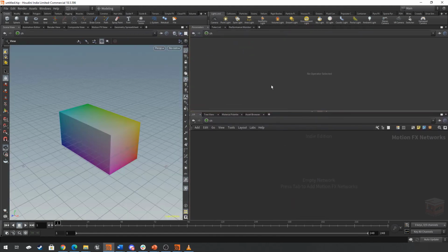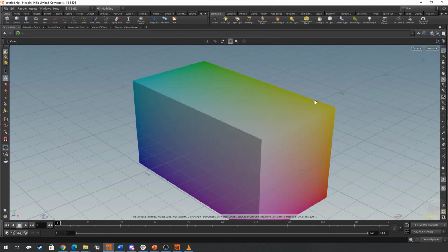the layout of Houdini. We can expand a particular type of window by clicking on the arrows in between the different panels. So if I want to expand this to almost full screen, I can click on this arrow to bind it to the right. This will collapse the right panel, or panel set, into basically this bar.